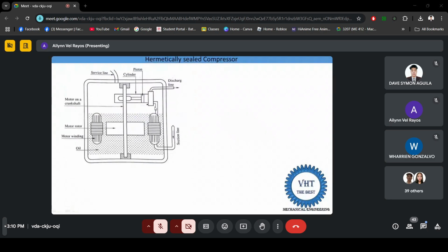Again, in these same figures, you can see that in the motor the copper winding is directly exposed. This winding is open. When this motor is in a completely sealed unit, the motor gets heated. So how is this heat rejected? The heat removed from the motor is absorbed by the oil, which is known as the cooling oil. As well, the refrigerant from the evaporator comes in at low pressure in the vapor state, and it passes over the winding of this motor.